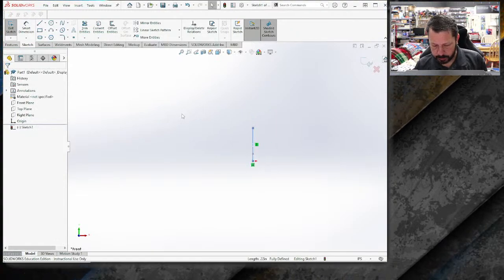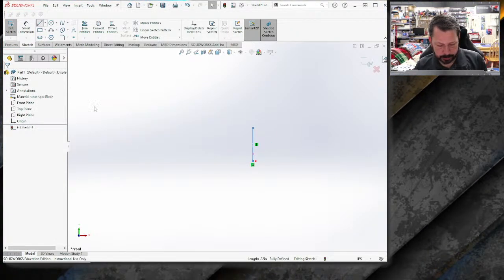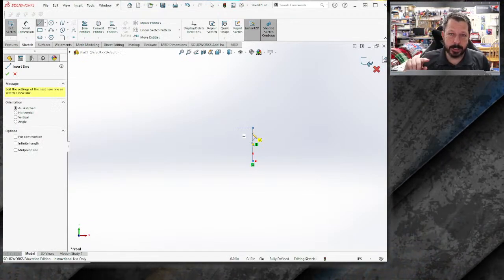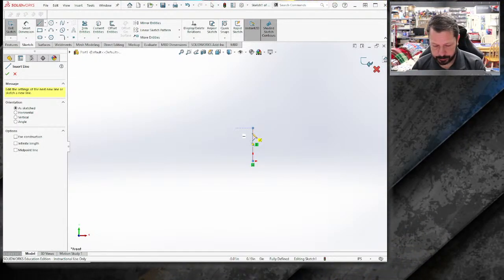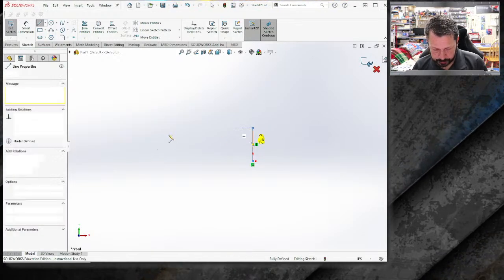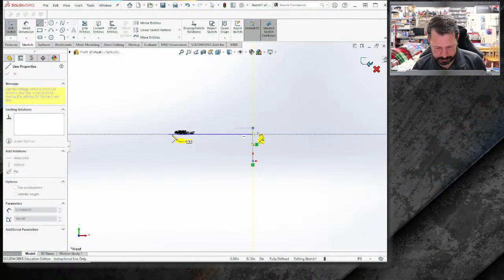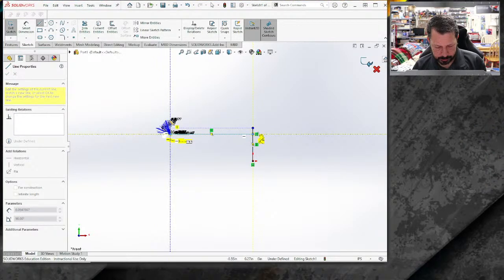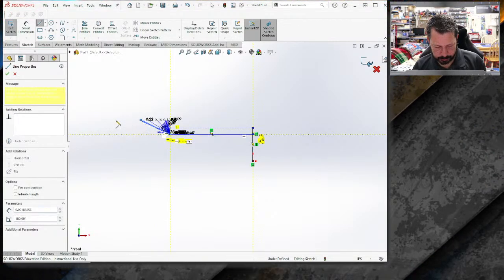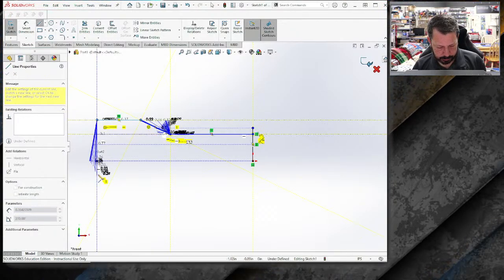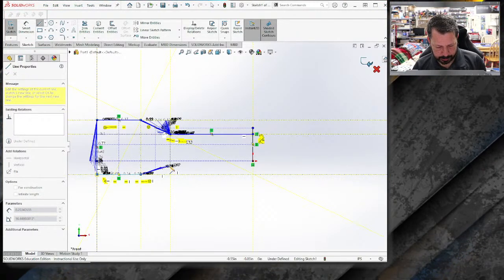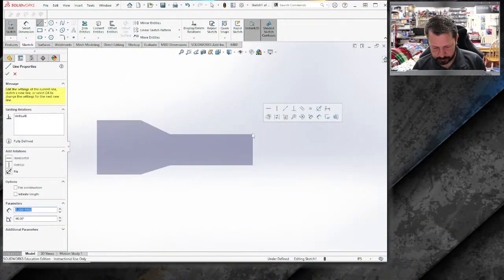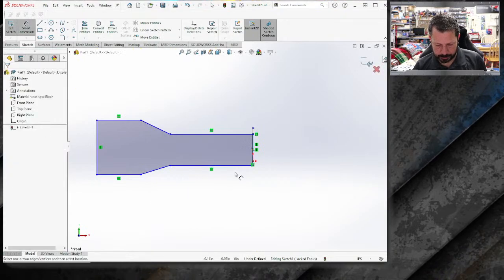All right, now off of this, let's build. We actually have quadrant symmetry here, but I'm just going to use half symmetry. So we'll be able to line out here. See, this redraw makes it kind of hard to see what's going on. We'll just put an angle over here, and we'll put some dimensions that kind of keep it right. All right, so let's dimension this guy up.